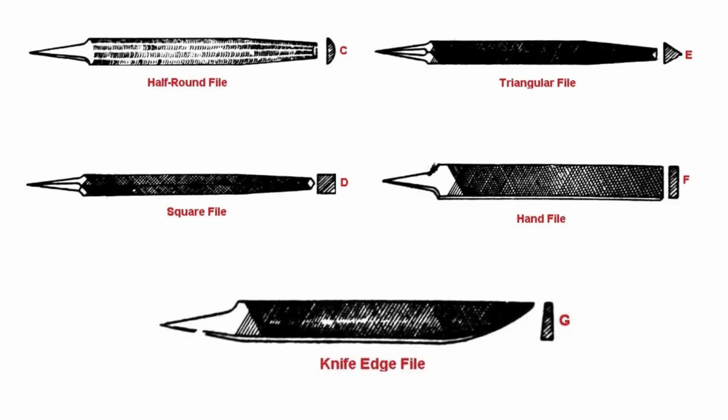Now here you have certain files, that is the half round file. It is flat on one side and curved on the other side. The double cut teeth are cut on it, and like a round file, it is also tapered. With this file, a damaged hole can be set in order again.